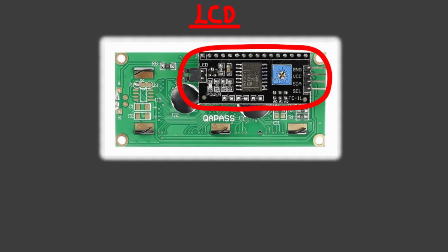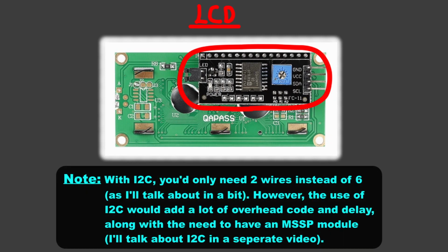Also, you'll see many LCDs that come with an I2C interface. The LCD is still the same, only it's connected to an I2C to parallel converter. Unfortunately, the library is only built to directly connect to the LCDs. Maybe I'll add the functionality to use I2C in the future, but for now you won't be able to use those.